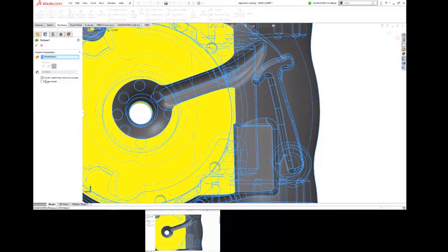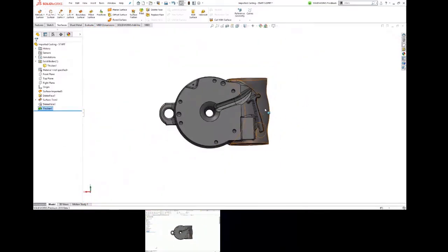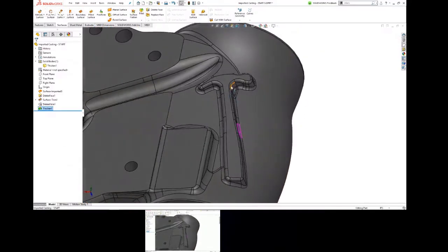Yeah, in our case, as soon as I choose this option, notice how it overrides the thickness value. So this is one of those where certainly the UI designers probably did their best to try to explain that, but it's a dual purpose command. If I want to make that a thin wall type of piece, then I just enter my value here. Create solid from enclosed volume gives us the result we want. This hammer feature that's on the back, that's a mess, and I'm going to leave that for homework if anybody wants to try to clean that up.